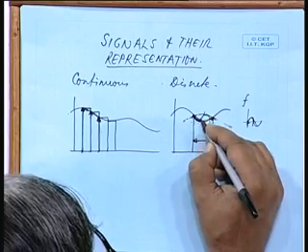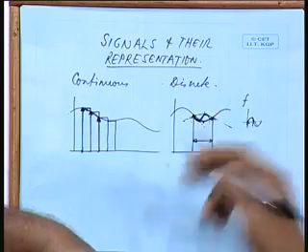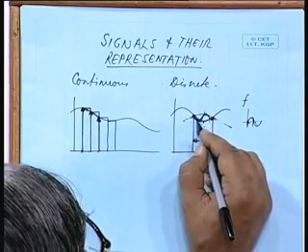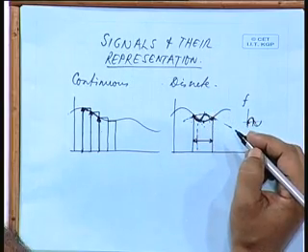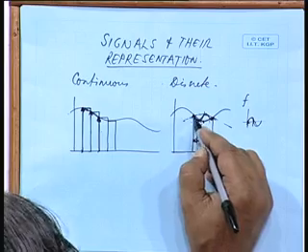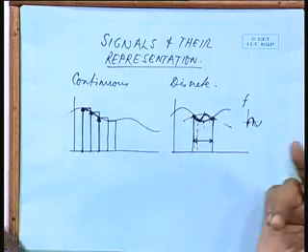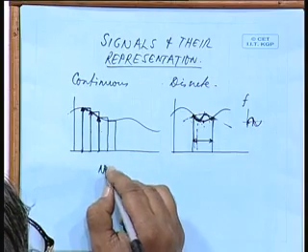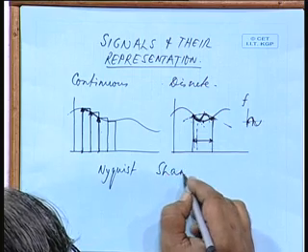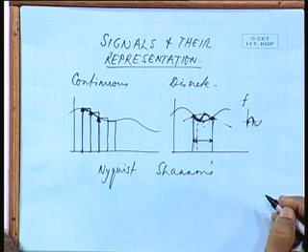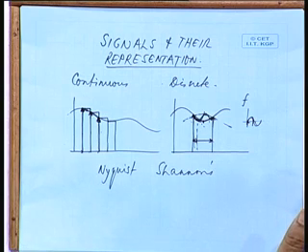There can be some more changes, okay. There can be a peak and trough both, then that means it is varying at a much higher frequency. So, I must reduce the sampling time further to trap that change, otherwise the sampled value will not be representing the original signal. Is that all right? So, this is a very famous theorem, Nyquist or Shannon's sampling theorem. Okay. That means, the sampling rate should be at least twice the maximum frequency present in the signal.